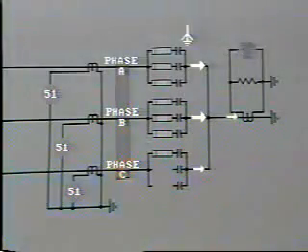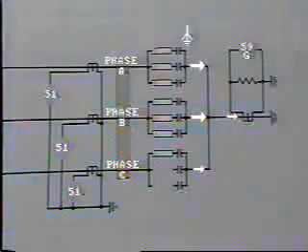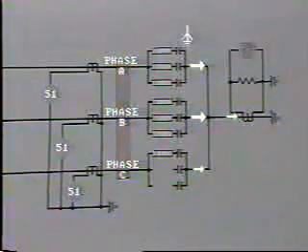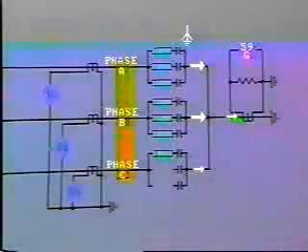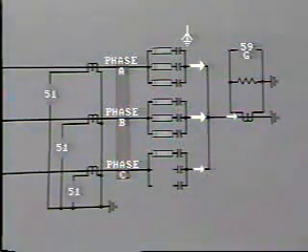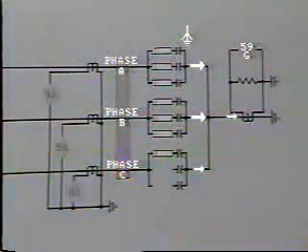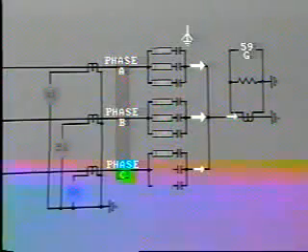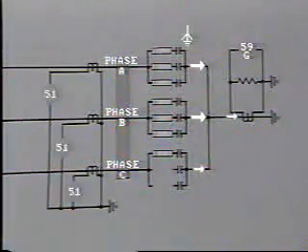This can be detected by the installation of an overvoltage ground relay, 59G, which will function to alarm the operator. Additional backup protection may be provided by overcurrent relays, 51, connected between the line and the capacitor bank.